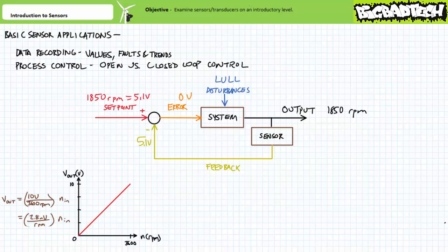In conclusion, this lecture took a brief introductory look at sensors or transducers. We examined various methods of transduction for pressure, rotational speed, fluid velocity, flow rate, position, level, vibration, and temperature. Additionally, we discussed transfer functions and the process of adjusting the zero and span of a particular sensor. Finally, we examined how sensors are employed in closed-loop controllers and how closed-loop controllers can automatically correct any errors and compensate for disturbances. Remember to review these concepts as often as you need to really drive it home.